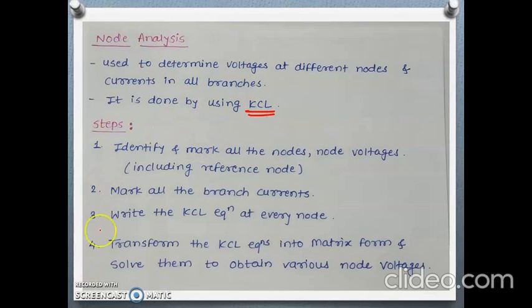And what are the steps in nodal analysis? The first step is, when we are given a circuit, we first identify and mark all the nodes and node voltages, including the reference node. In the first step, we identify and mark all the nodes and node voltages.